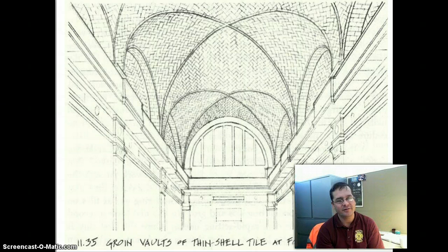So the upshot of this is, under traditional methods, you could only construct this with a wood false work. You'd have to build the structure out of wood, cover it with brick, and then somehow remove the wood, which was holding up much of the weight of the brick. A traditional approach to that would be to burn the wood formwork out of the way. With this corbelling technique, the entire structure could be created without false work, and that substantially reduced the cost of construction. And remember, the name of the game in construction is making money.